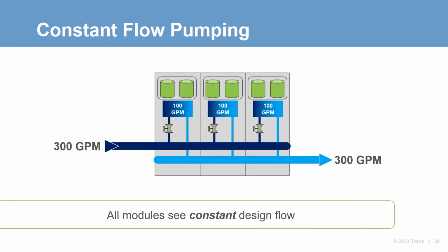In contrast to the previous system, where a chiller seeing flow would typically be operating, the chiller, or all 3 modules, see a constant design flow rate and stage compressors on and off to maintain the desired leaving fluid temperature. The temperature of the fluid leaving the chiller will be dependent upon the return water temperature and quantity of compressors in operation, as Esti described earlier. When the chiller is below fully loaded, the leaving temperature is a mixture of conditioned and unconditioned fluid.